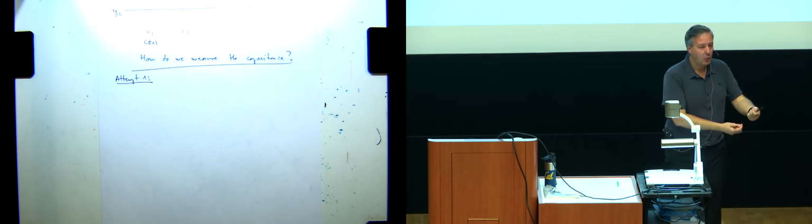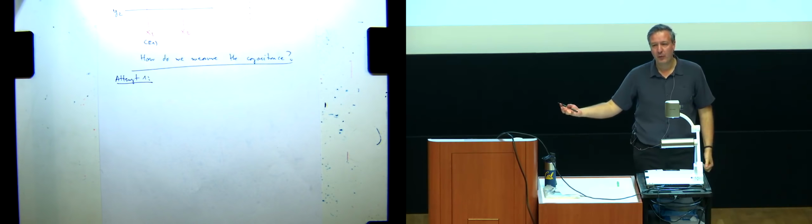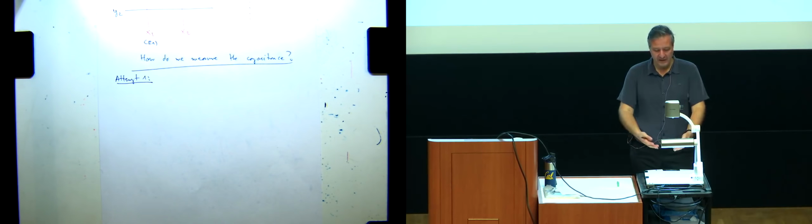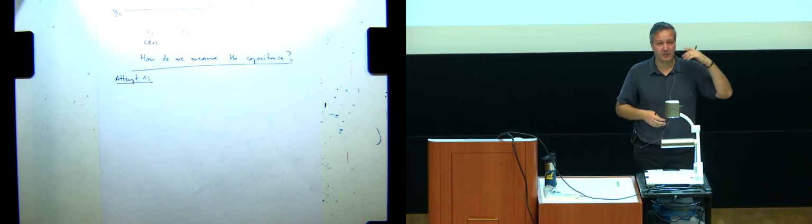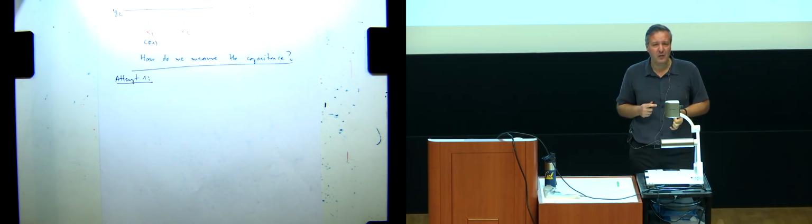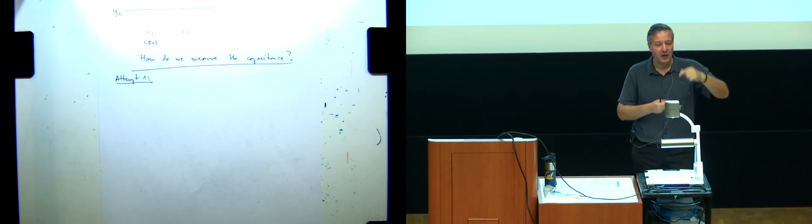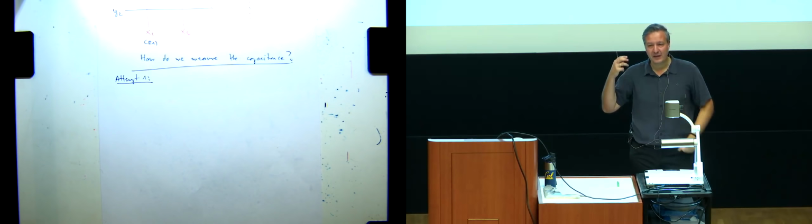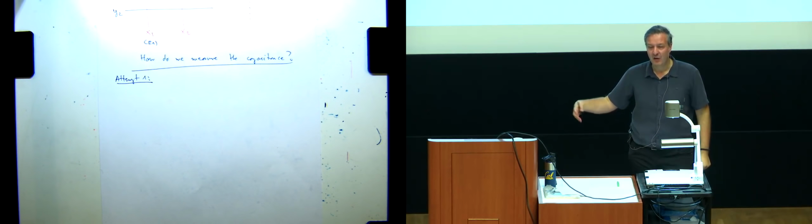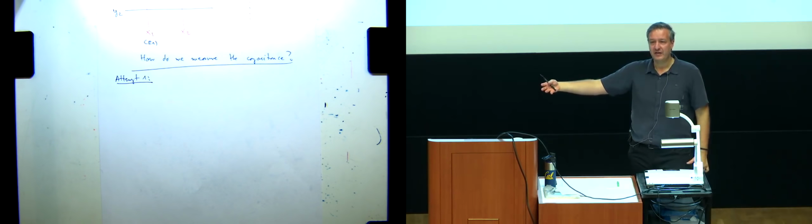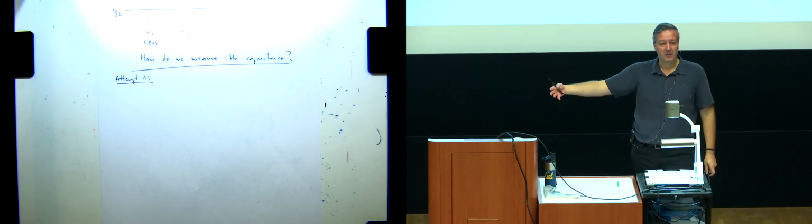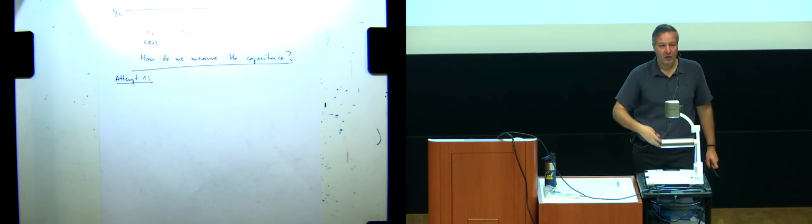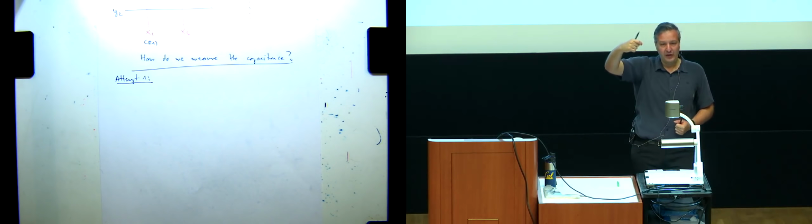We have some physical quantity. To which quantity do we want to convert it? In this case, it's a capacitance. It could be distance. That's what we did with the resistive touchscreen. We had distance. We converted that somehow to a change in resistance. And then we converted that change in resistance into what quantity? Voltage. Here, we have, again, distance, which is the location of our pixel.